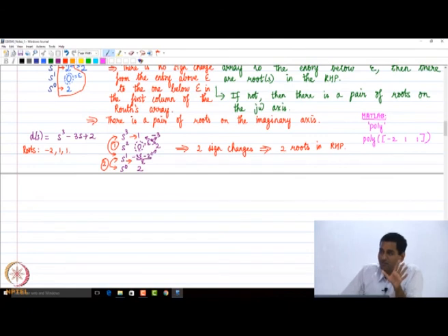That's a good point. I hope everyone got it, right? So if you give this polynomial to me as a denominator polynomial of a transfer function, just by observation I will say that the system is unstable. I don't even need to construct the Routh array, because I can see that the necessary condition is violated. That is, all coefficients must be non-zero and of the same sign. But then our task here is to just construct the Routh array and learn. Okay, so that is the idea.